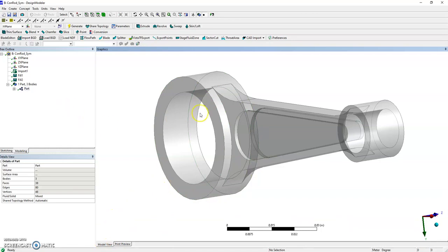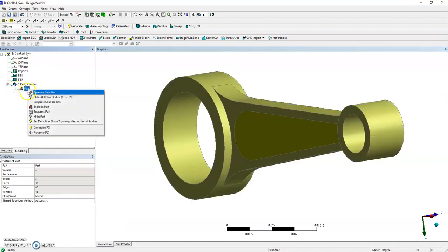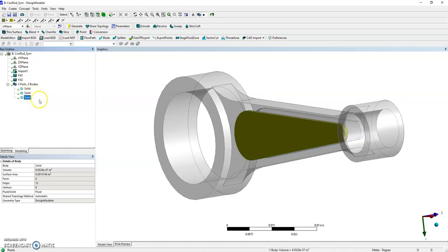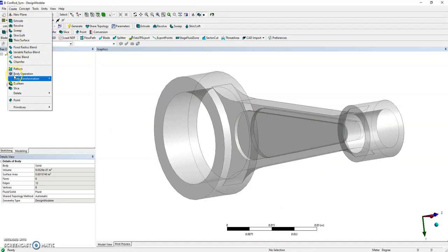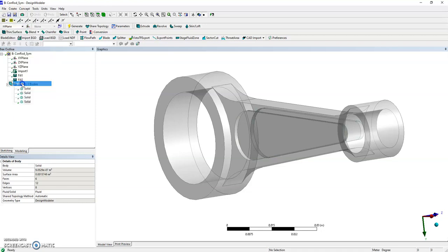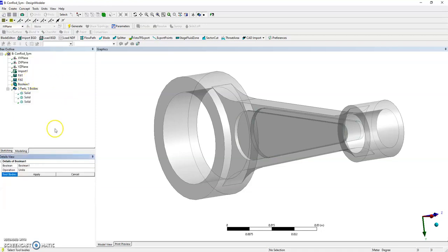Right, still, having the form new part has not worked so well. Not that I wanted that anyway. I need to explode the part and we go back to what we did before. The tool I want is Boolean. Boolean is going to allow us to add and more. The operation I can do is unite them all together, or you can do some clever tricks with subtract, imprint as well. But I don't want to do that. I want to unite.